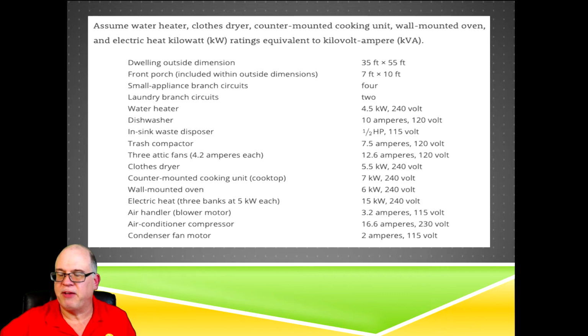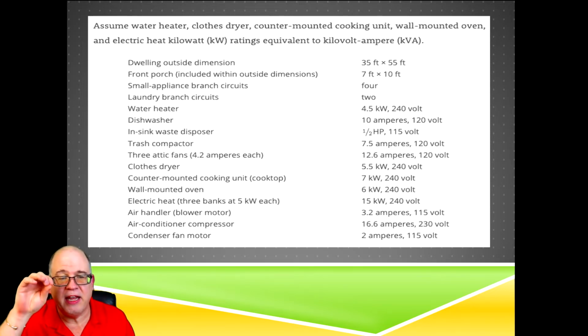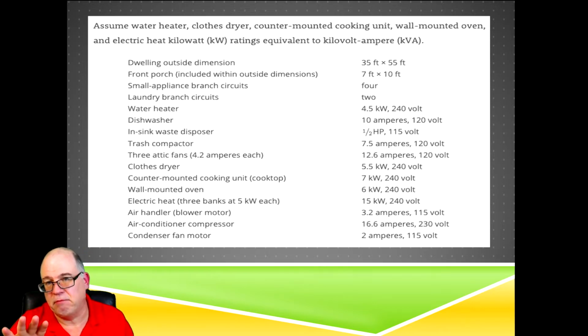If I was using fixed space heating like baseboard heating, then it typically wouldn't have the blower motor associated with it. Okay, in our question, we are going to associate the blower because it's used to blow the cooling, but in our case, the way this heat is set up, it is also utilized and they're separately controlled, but it also figured in blowing that heat as well. So I'm just telling you that up front. If your exam has separately controlled baseboard heating, then it wouldn't have to add the air handler in that. Okay, just making that clear up front so there's no confusion.